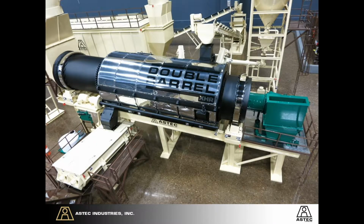Here's a double barrel plant. Lots of double barrels in the state of Virginia. You can see that we are actually pulling exhaust on it. And here's the drum itself. This particular one has a pug mill for external mixing, and you got your burner on this end.